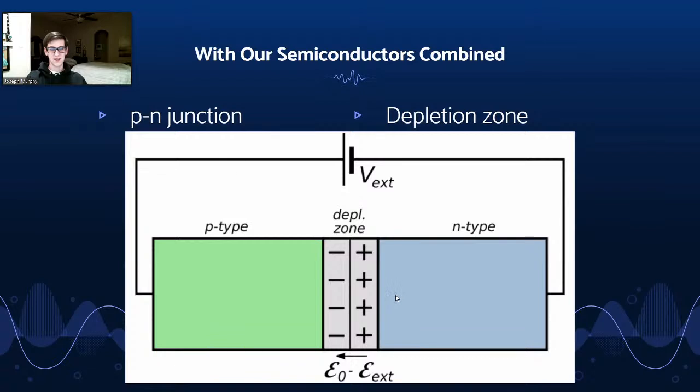Now you would think that since the n-type semiconductor started out with an excess of electrons and the p-type with a deficiency, electrons would move over from the n-type to the p-type after photogeneration. But again, we still have the depletion zone in between the two semiconductors, so a newly photogenerated mobile electron can't just move straight from the n-type to the p-type semiconductor.